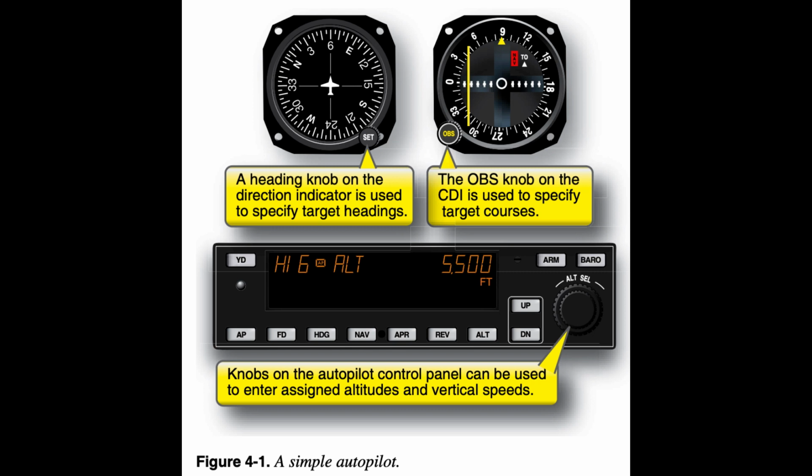Most autopilots have indicators for the amount of servo travel or trim being used. These can be early indicators of adverse conditions, such as icing or power loss. Rarely will a trim indicator ever indicate full travel in normal operation. Consistently full or nearly full travel of the trim servos may be a sign of a trim servo failure, a shift in weight resulting in a balance problem, or airfoil problems such as icing or inadvertent control activation.